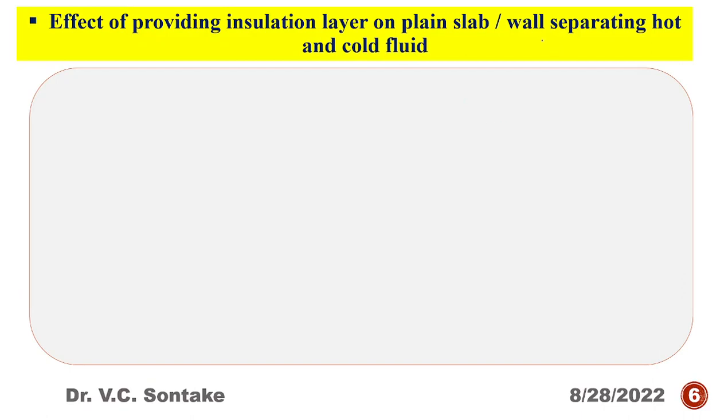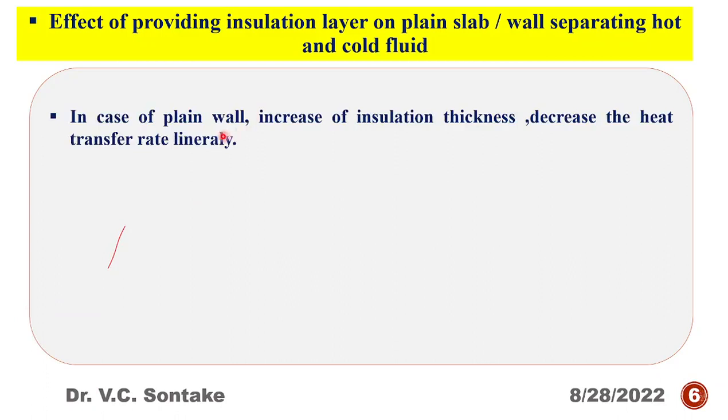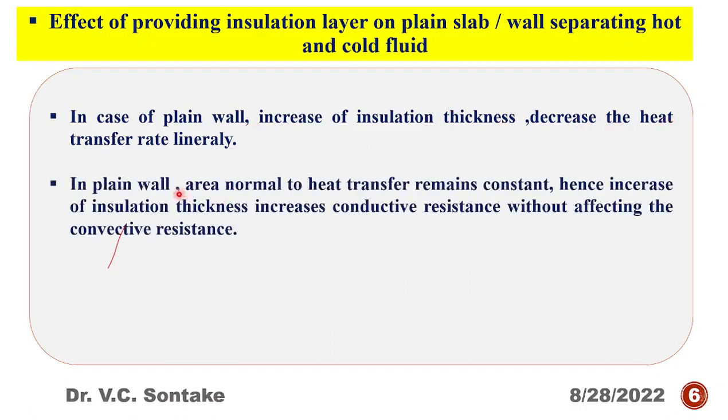So I can summarize the effect of providing insulation on plane slab or wall separating hot and cold fluid. In case of plane wall, increase of insulation thickness decreases the heat transfer rate linearly. In plane wall, area normal to heat transfer remains constant even when I provide the insulation layer.